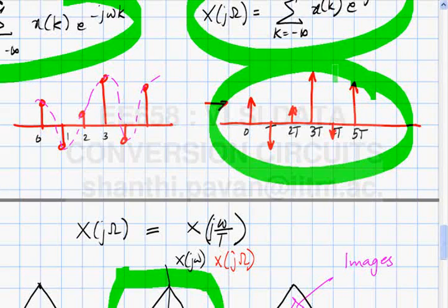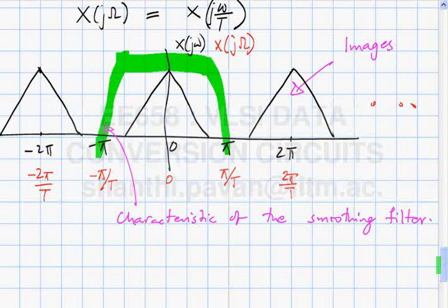Of course, it's very difficult to generate the impulse, fine, and more important, even if you generated the impulse, it's such a terrible waste of power, because what you want is only this energy here, and now you're generating this big, you're generating images all over the place, and also trying to get rid of it by putting a smoothing filter. So clearly from a power efficiency point of view, first of all it's difficult to do, and then it is inefficient, so why bother doing it at all?